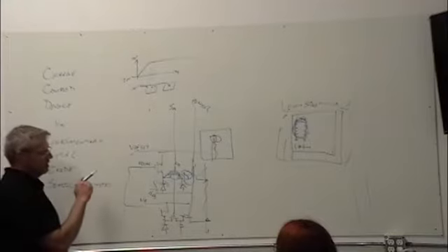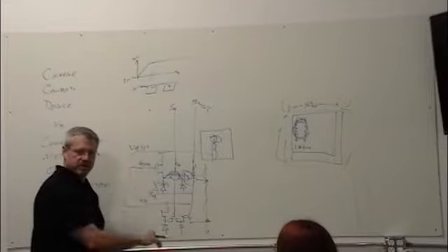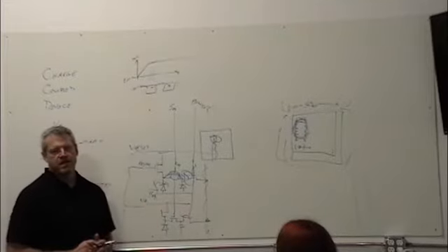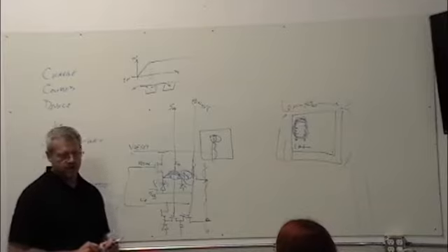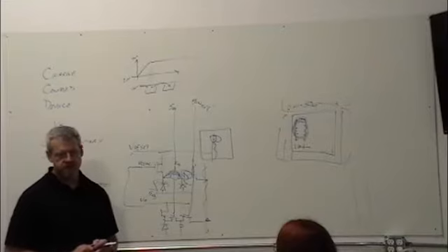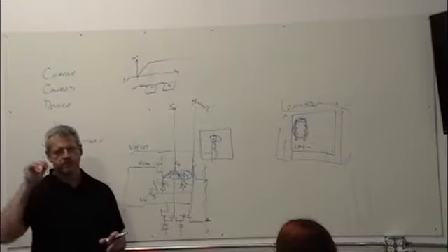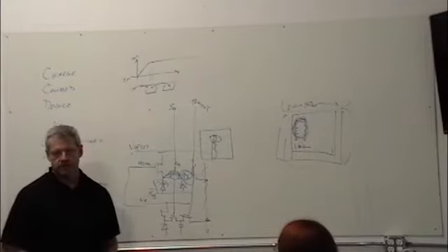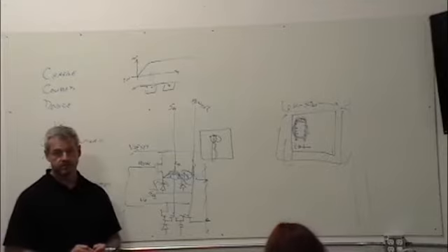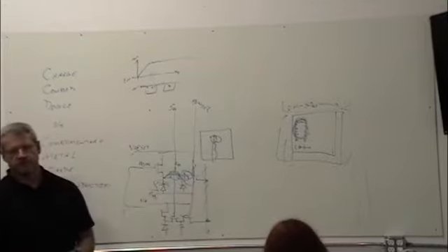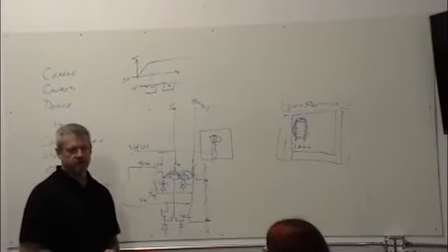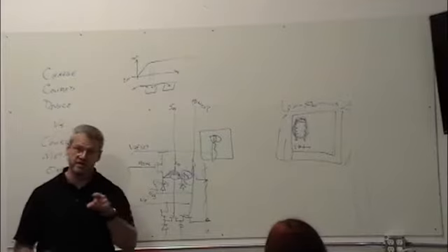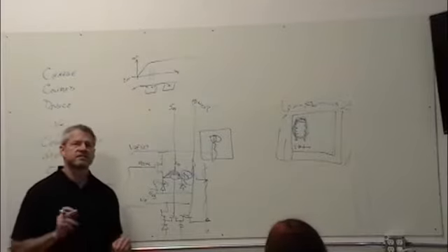Now, he's warm, there's a million of them on here, this chip's running warmer, it's got more noise. If you cool them, I've read some papers where they talk about scientific grade CMOS sensors. I think they're usually looking out at infrared, not visible, but they're down around maybe 5 electron noise, 10 electron noise. Really good. CCDs, I still look at those. Some of the stuff that we used to work with, we were calling sub 5 electron noise. I mean, we were able to photon count. One of the other neat things, Texas Instruments came out with something.